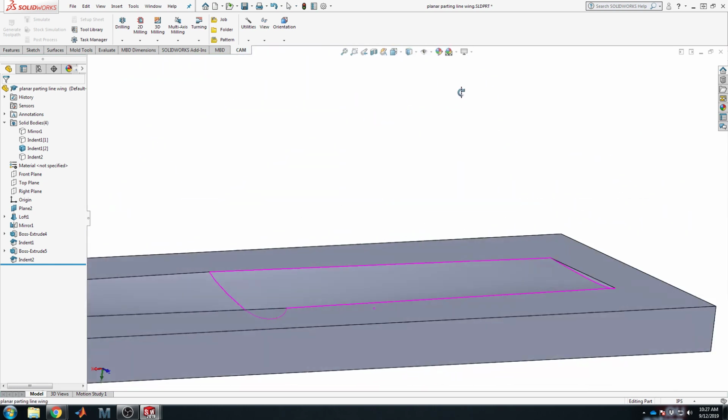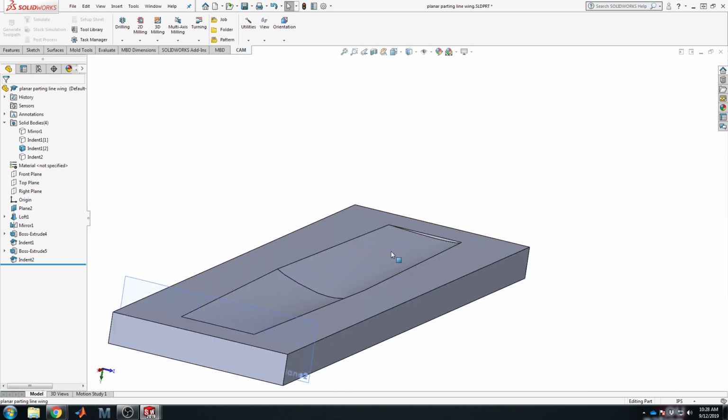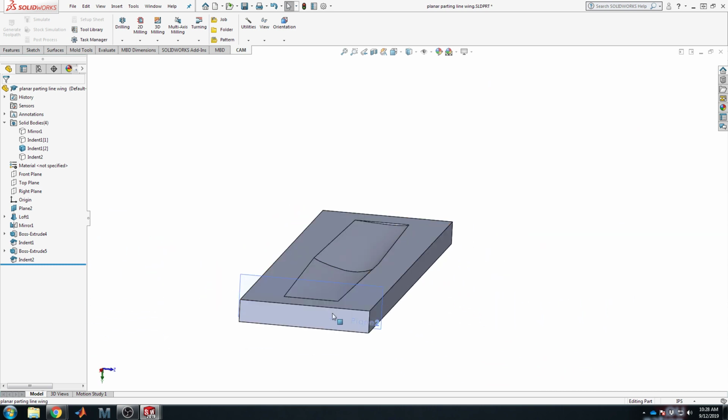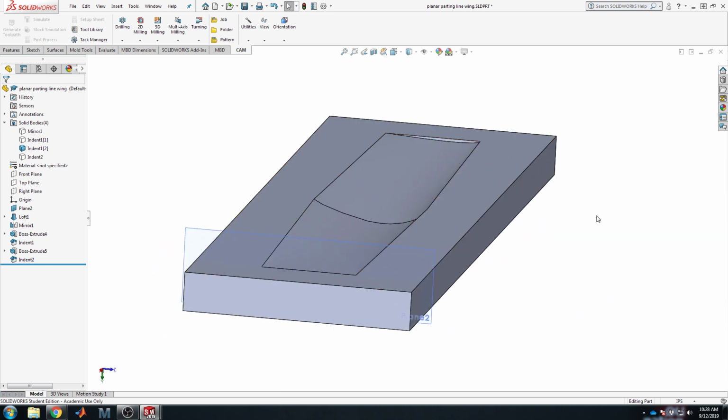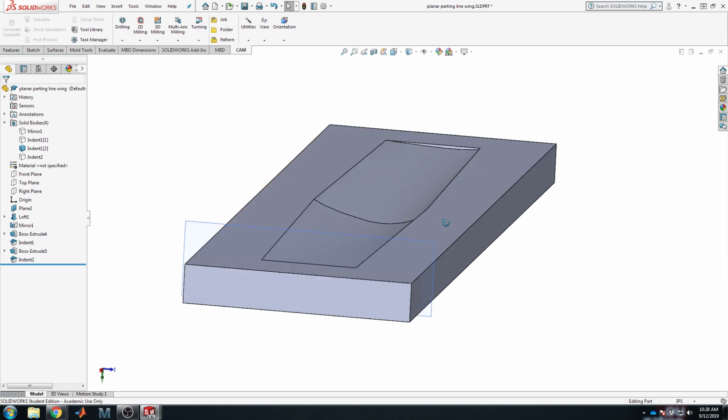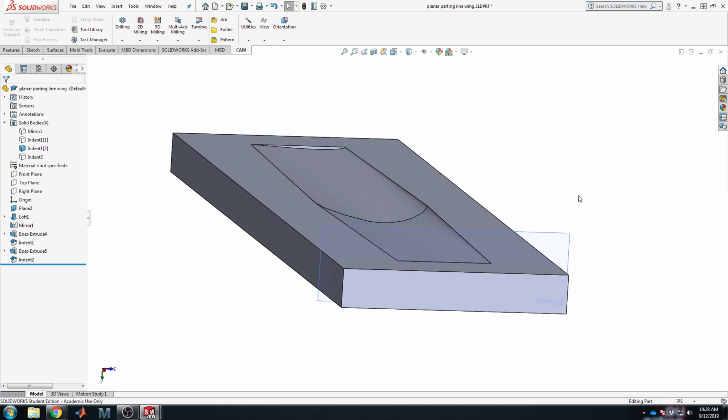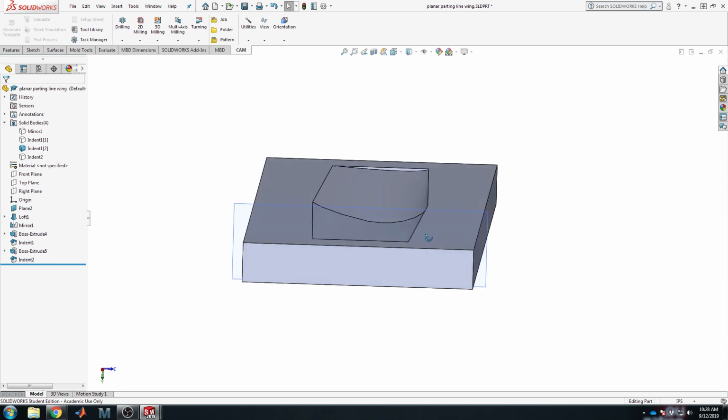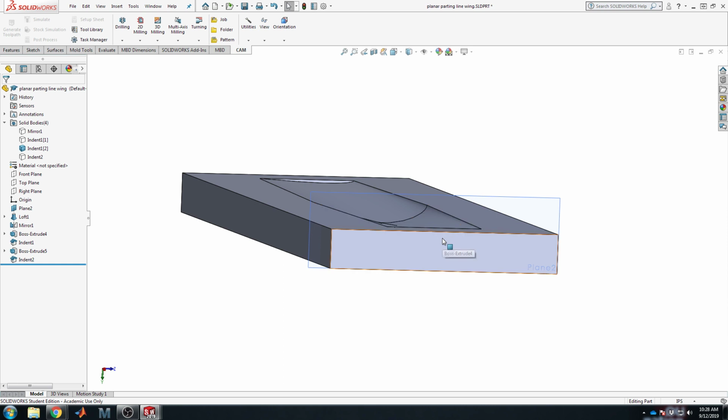We'll actually be using the top mold because it's simple. We'll start with making G-code, and the machine code is what that is, auto-generating the paths to machine this part out, because this is really indicative of probably definitely more than half, but most simple molds are just a simple cavity. I mean, you don't want to have any over vertical elements. Undercuts is what they're really called.